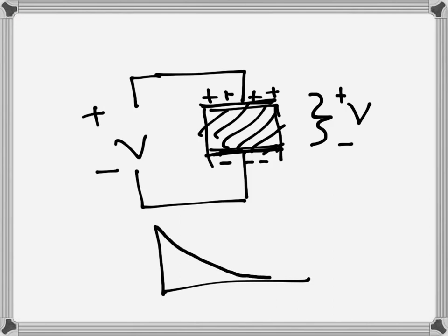It decays exponentially, and the initial current is basically, if there is an R in the circuit, which there should be, because a capacitor is not connected directly, and the connecting wires are there as well. So the initial current is basically V over R, because we have used V here. That is the initial current, and the final current is 0. So then it's blocked, and as a result charge is stored across the capacitor, and energy is stored inside the capacitor.